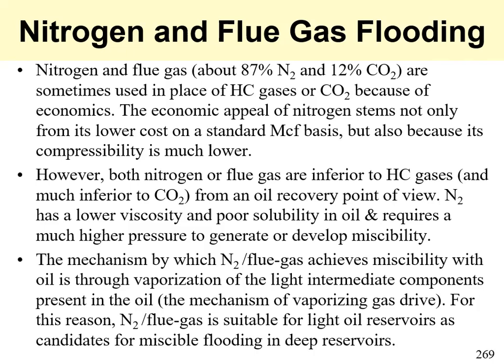As regards nitrogen and flue gases, the economic appeal for their use stems from the fact that they cost lower on a standard 1,000 cubic feet basis as compared to hydrocarbon gases or CO2, and they also have a lower compressibility. However, they are inferior to the other gases from an oil recovery point of view because nitrogen has a lower viscosity and it has poor solubility in oil.